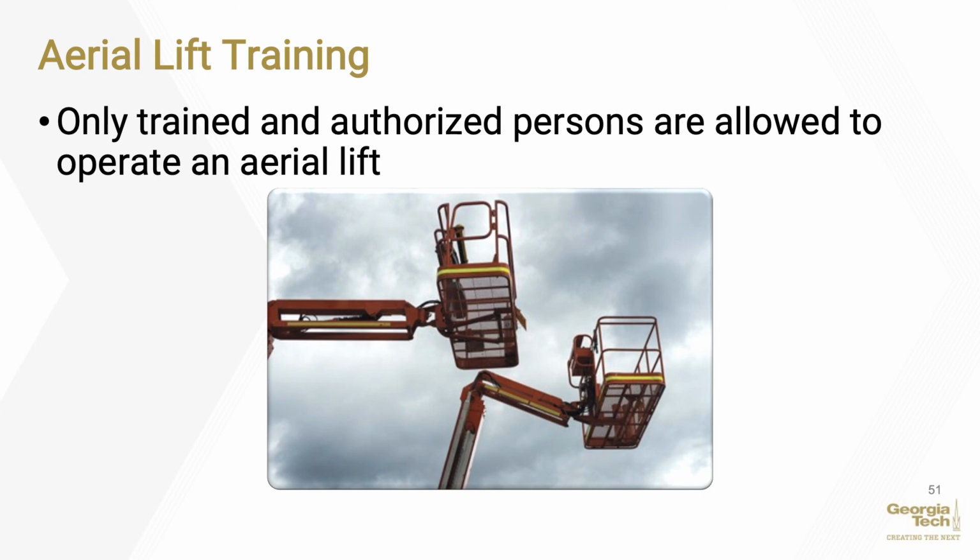Workers should be retrained if any of the following conditions occur: an incident occurs during aerial lift use, workplace hazards involving an aerial lift are discovered, or a different type of aerial lift is used. Employers are also required to retrain workers who they observe operating an aerial lift improperly.